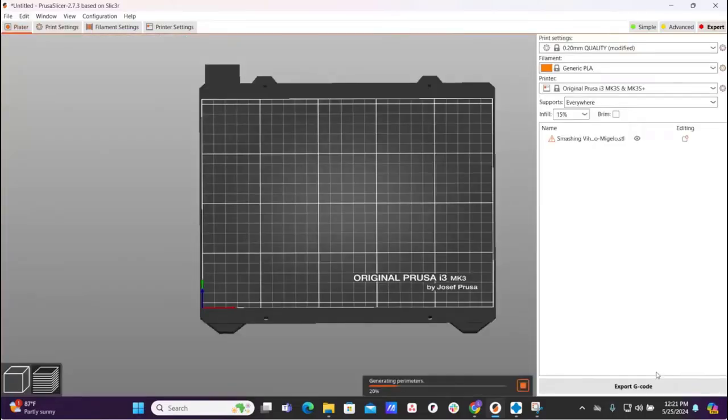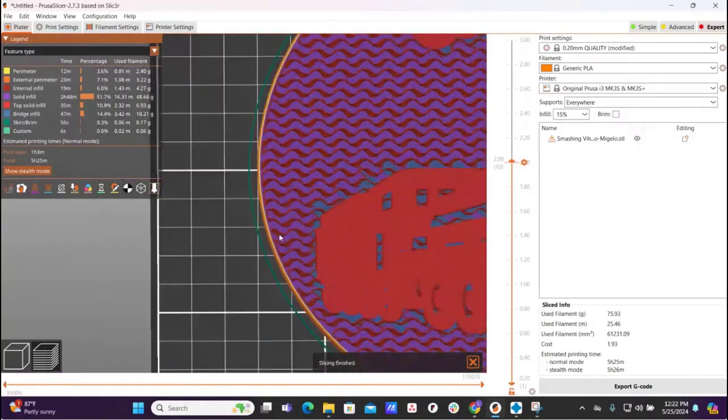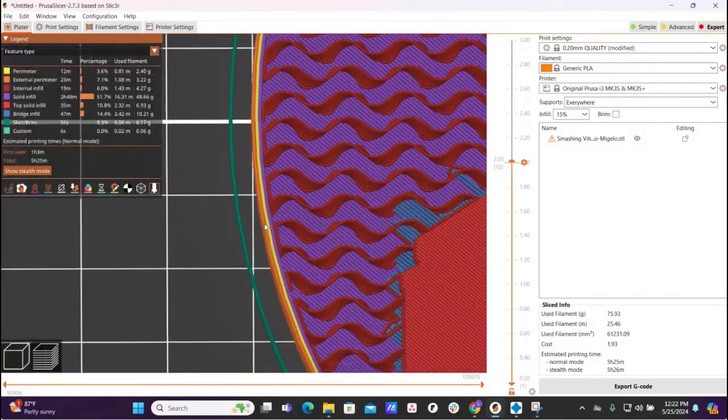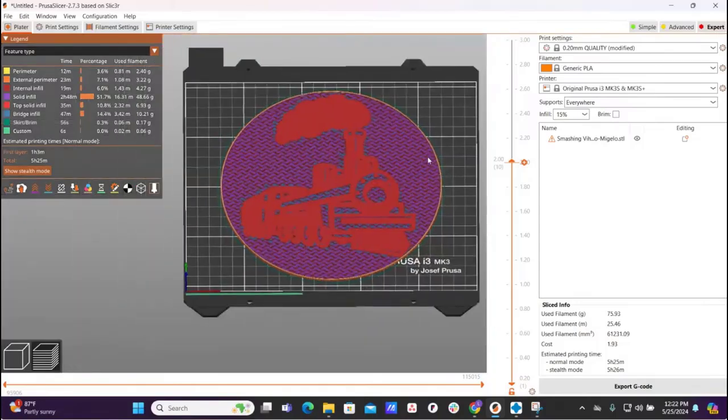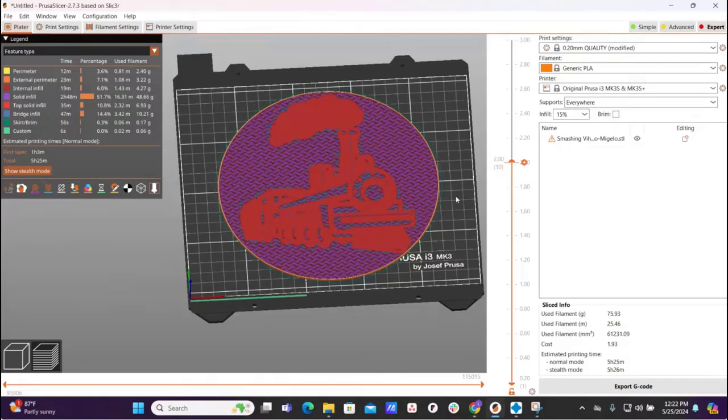So in this example here, there is a solid piece of plastic that outlines the entire shape. If you zoom way in here, there's an orange and a yellow. That's 2 perimeters. If this was a skinny object and I wanted to make it stronger because I'm worried about it breaking, as I add perimeters, you will just get more of these rings that surround the perimeter of the object. So just as an aside, if your prints are breaking, add more perimeters. It'll help.